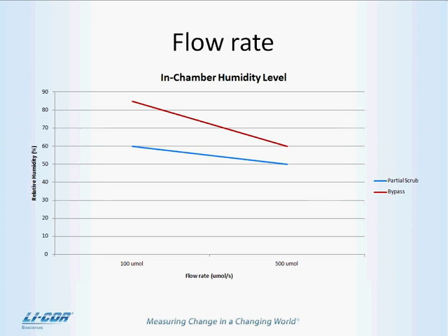It's going to slow your measurement slightly, since it takes longer to flush the chamber when you slow the flow rate, but good humidity levels are maybe worth a slightly slower measuring process, especially if you're in really arid measurement environments.